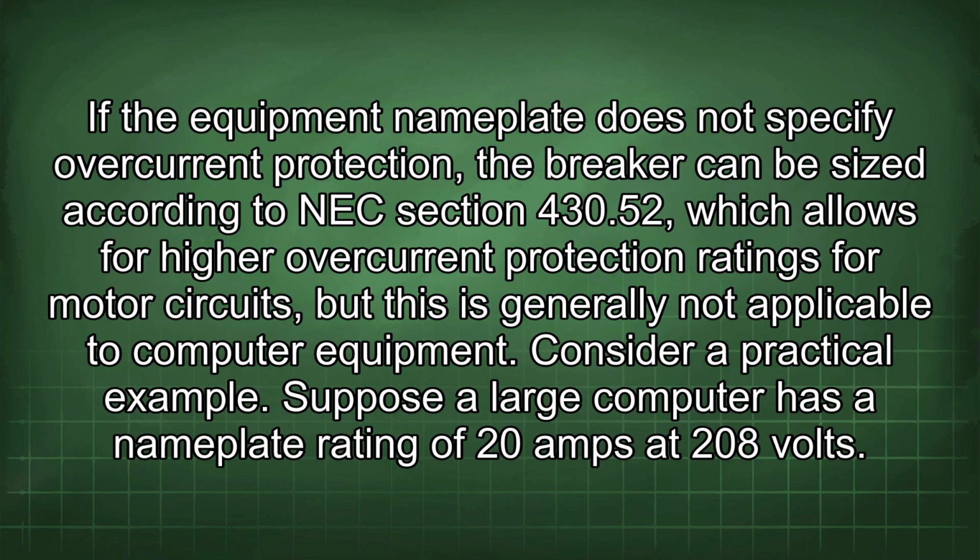If the equipment nameplate does not specify overcurrent protection, the breaker can be sized according to NEC Section 430.52, which allows for higher overcurrent protection ratings for motor circuits, but this is generally not applicable to computer equipment.